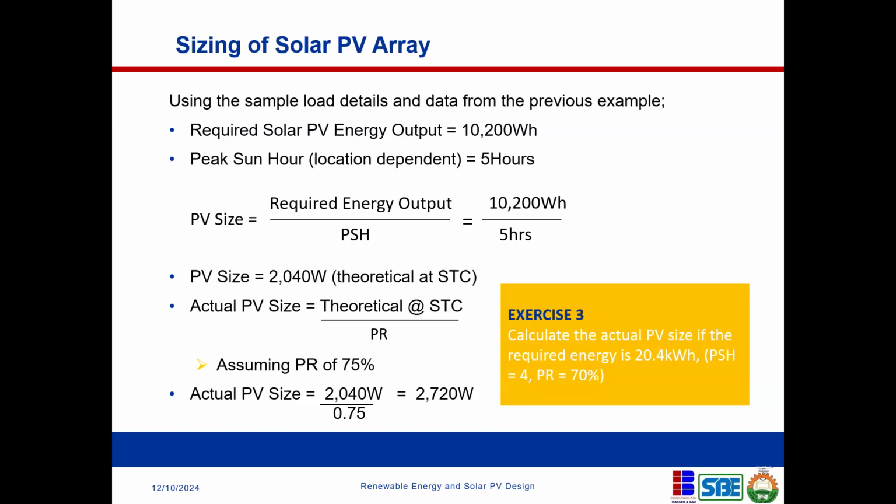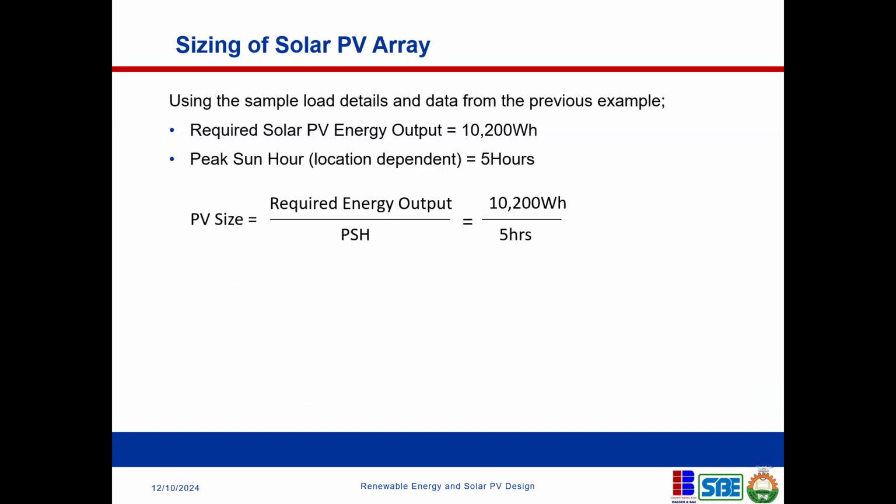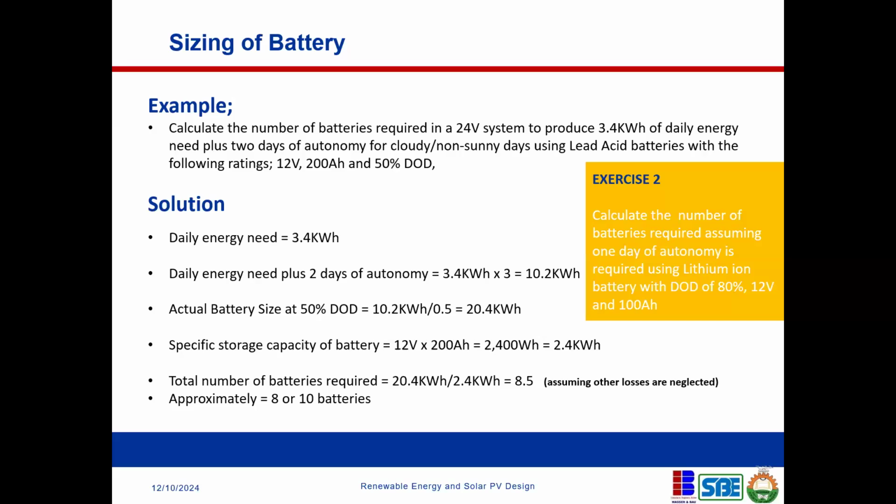Okay, let me talk about batteries. Because I know when I talked about battery, I also assumed that maybe some of the losses, the cycle losses, when you charge and discharge, there are losses. Why I say these are negligible is that they're not significant. It can be maybe, like I said, 95%. So just about 5% losses, right? So they're not much. In some cases, it might be just about 5%, in that range.